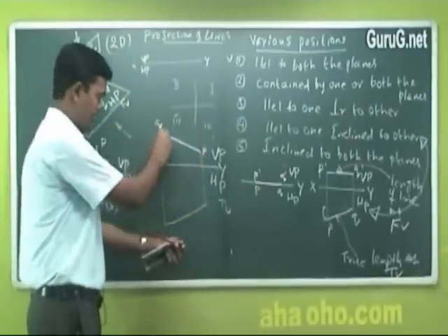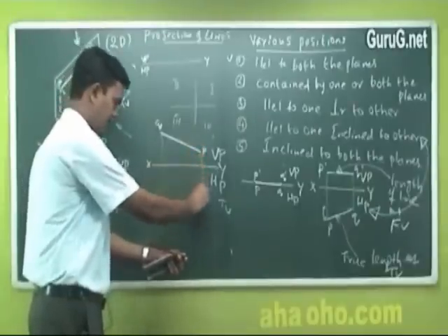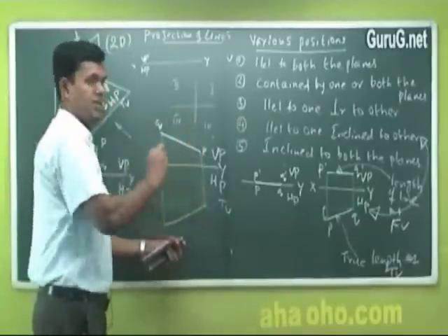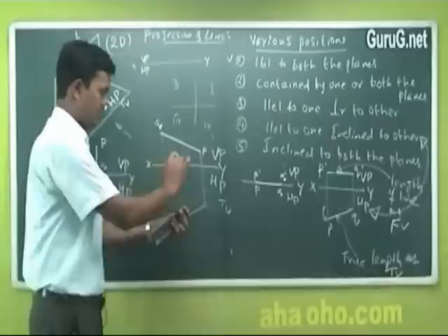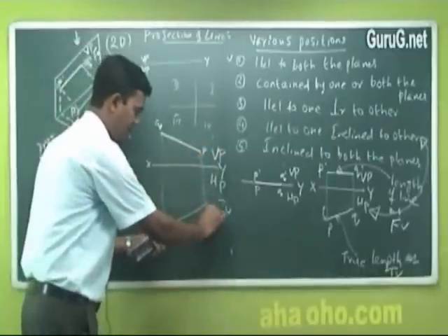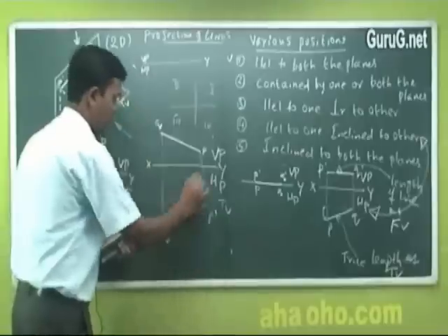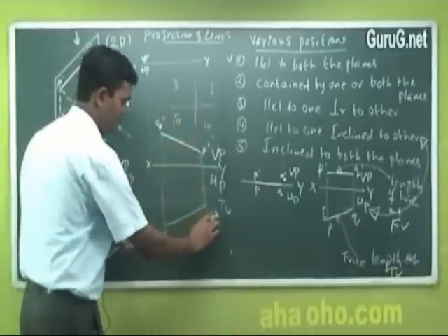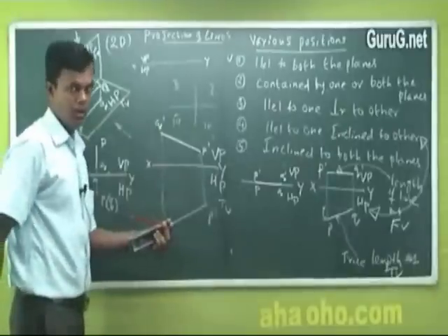Kindly remember, this line is called the projector line. It is the image of that point on the opposite side. It's just the projection of point P as P dash, or Q as Q dash. Always write the dash in the front view, P' and Q' here.